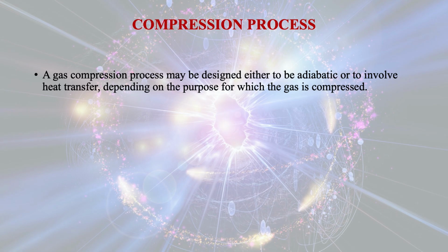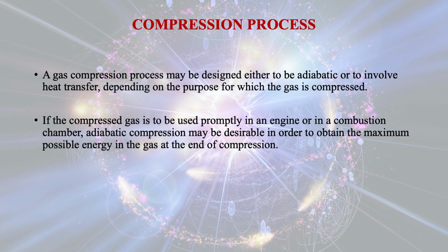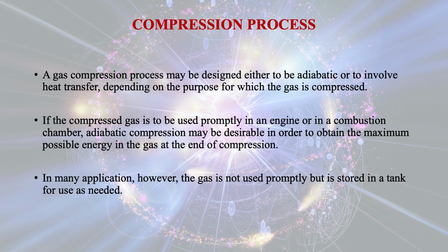Let us discuss the compression process. A gas compression process may be designed either to be adiabatic or to involve heat transfer, depending on the process for which the gas is compressed. If the compressed gas is to be used promptly in an engine or in a combustion chamber, adiabatic compression may be desirable in order to obtain the maximum possible energy in the gas at the end of compression. In many applications, however, the gas is not used promptly but is stored in a tank for use as needed.